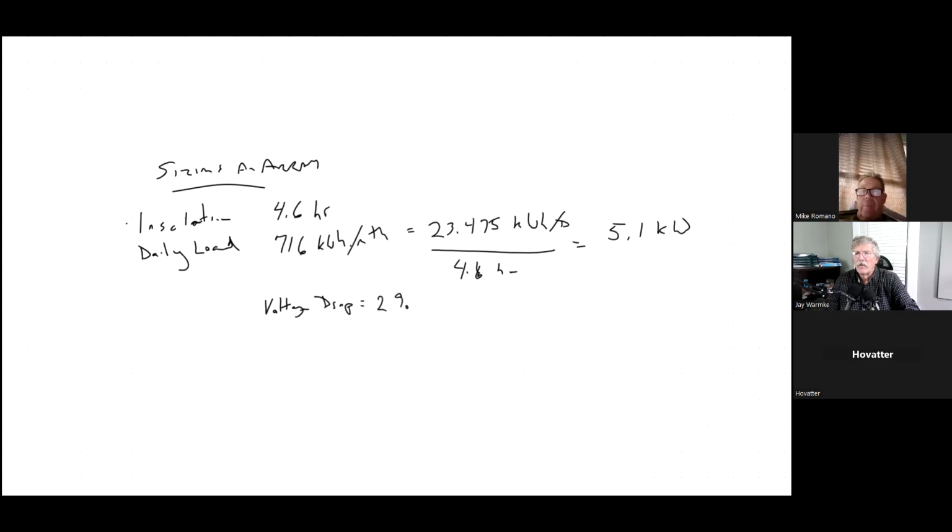We've got our inverter inefficiencies. And in most of the world today, that's going to be about another 2% based on microinverters or inverters. You've got soiling, there's a certain amount of loss due to soiling. That's just dust and stuff on the panel. So let's say that's about 1%.